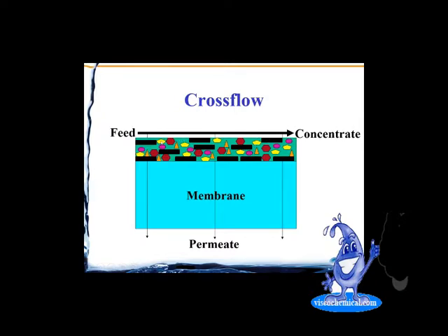The suspended particles, living and non-living, like silts and clays and bacteria, colloidal silicas, anything that is particulate in nature, can be deposited on the membrane. The permeate drag, the water molecules here, will tend to hold them down onto the membrane. Again, this is what we're calling fouling, especially if it's serious enough to cause us to have to chemical clean and to spend a lot of time and money trying to correct this.